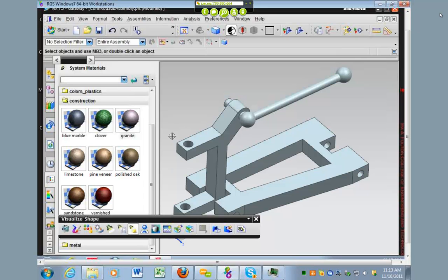Dr. Jensen, did you have something else you wanted to say? I was going to just make a couple of comments on the surface shell models. That generally, if you want part of your shell to represent windows, you're going to have to trim your surfaces in the shape of your windows so that you can easily go in there and apply different material properties to where the windows would actually appear.